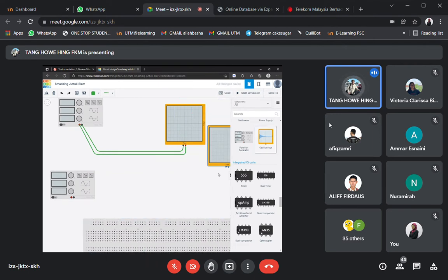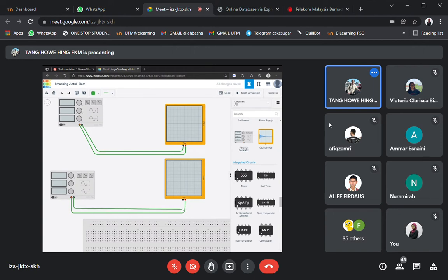And I also get another oscilloscope. Red to red, and then black to black. Because this round it is 100 kilohertz, the time per division I need to change. I think just a microsecond. 1 division is 1 microsecond, and let's see.